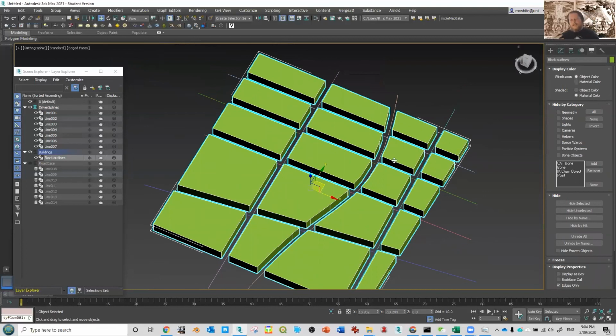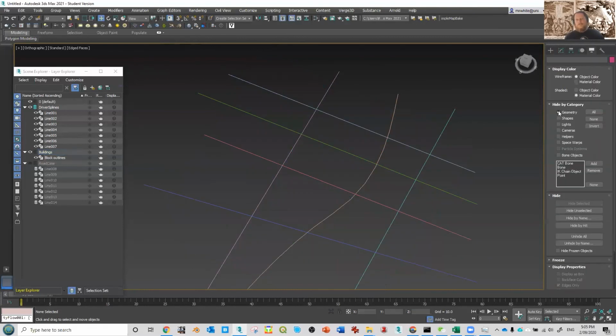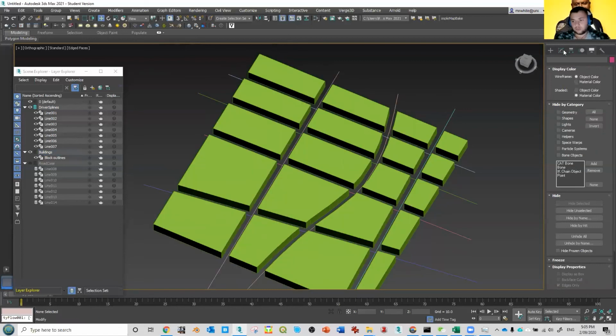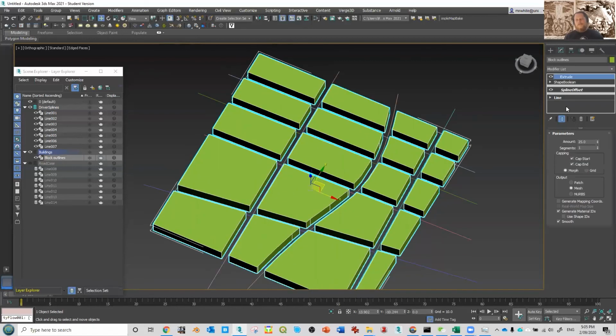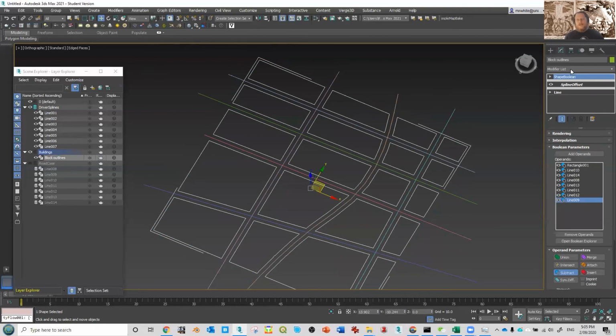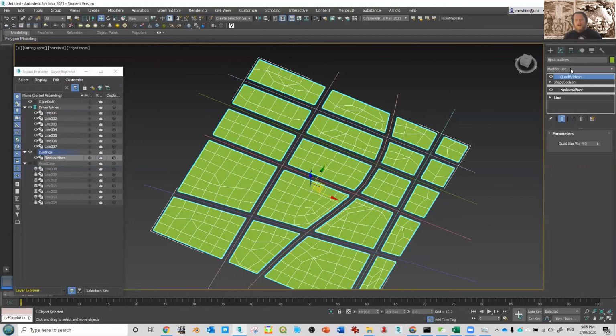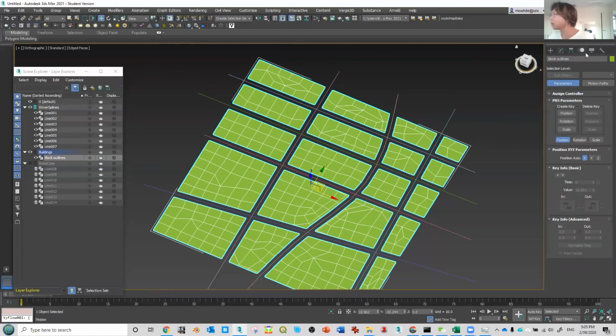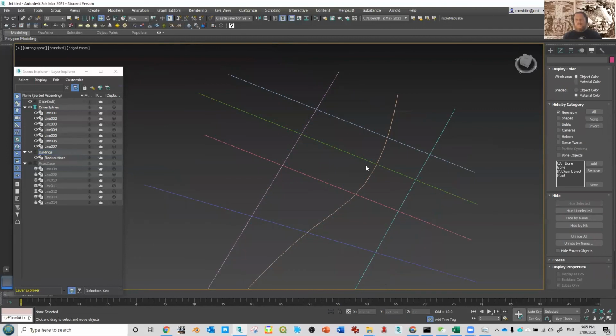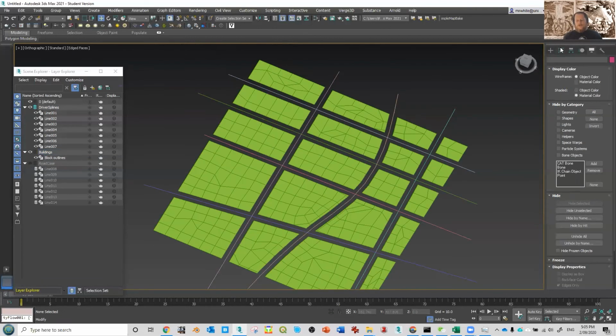No, sorry, I was just trying to say if you make splines into something that's a polygon mesh, for example extruding, if you've got that set to ticked, it just won't show. You don't need to extrude it. When you apply a quantify, it turns it into a mesh. So again, if that setting is turned off, it disappears.